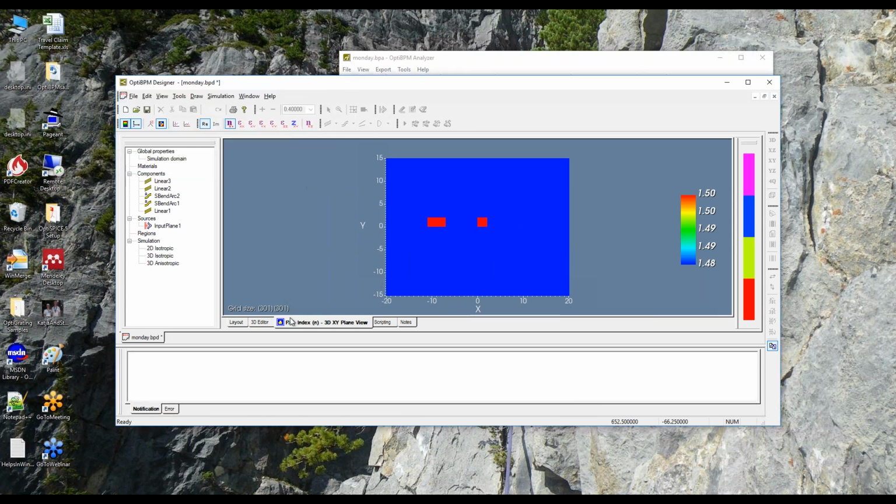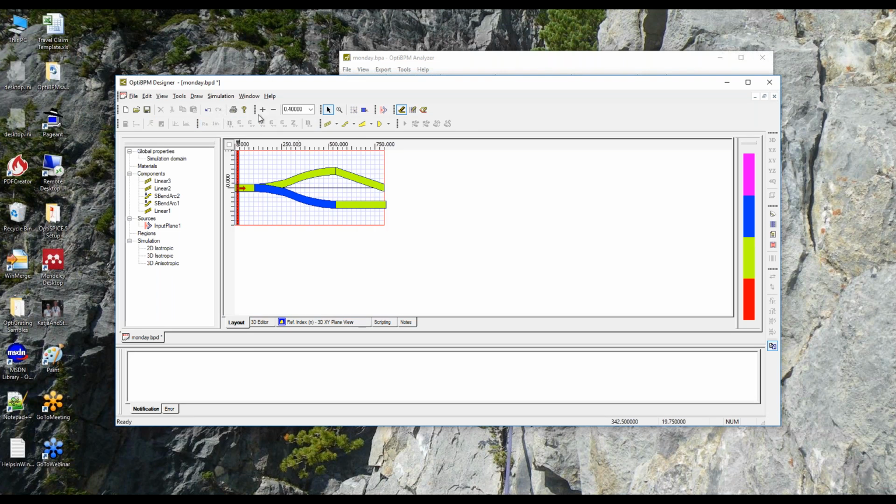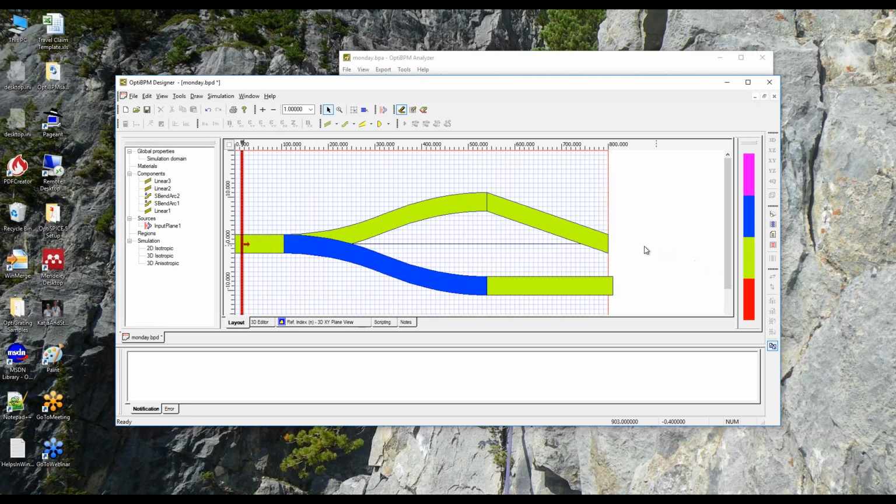Why? Well, it's hard to see, but if you zoom in about a zillion times, you'll find that only half the waveguide actually extends over the end due to the angle. People get stuck on that sometimes, so I just played it safe by sending it off the end. If only half the waveguide is presented at the end of the wafer, it might look for a mode there, not find one because it's not the refractive index distribution of the entire waveguide.